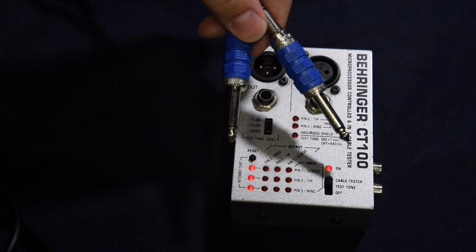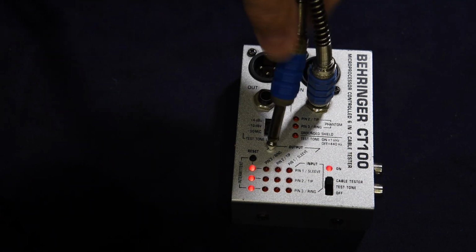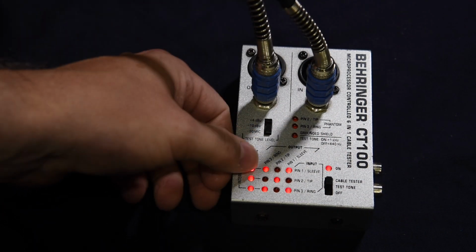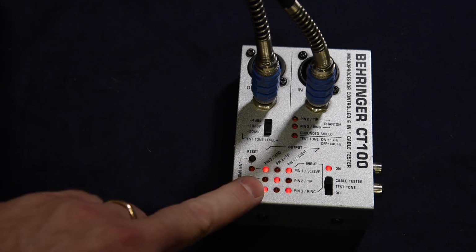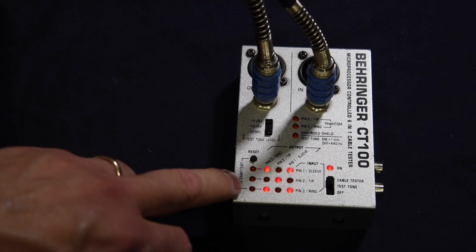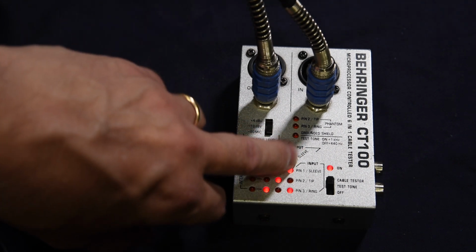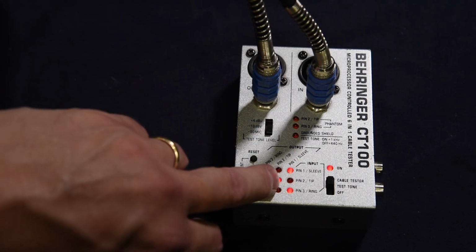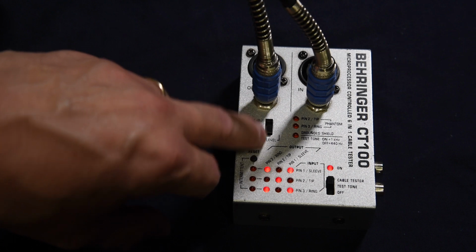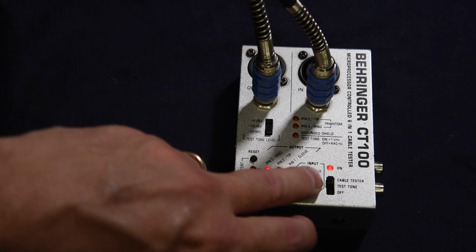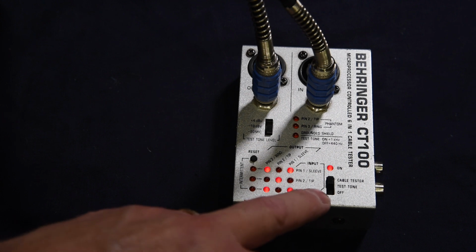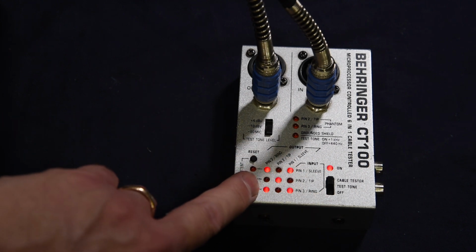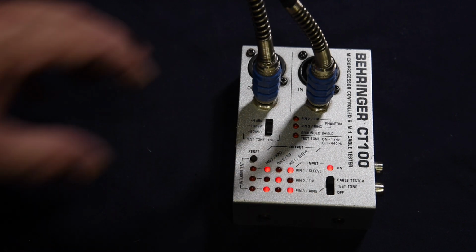And we'll now try a pair of mono jacks. Put those in. Hit the reset. Now you've got a different pattern. This time we ended up with a 5 dice-like pattern on there, and that's because we've actually got mono connections. So pin 1, the sleeve, is connected, pin 2 is connected to the tip, so that's the same. But when we have pin 3, there isn't a ring, so pin 3 is connected to the sleeve, and hence you end up with this pattern.